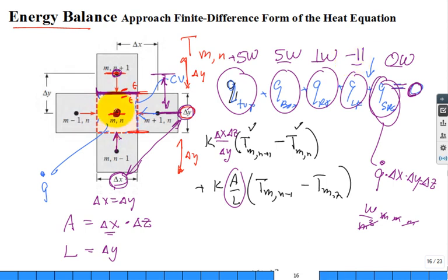So what you do is you get an equation, I call it energy balance for the node, let's say node 1. Then you get an equation for energy balance node 2, then energy balance node 3. You know what? If you have 10 unknown temperatures, you need 10 energy balance equations. Then, glad you took a numerical methods class, you'll have 10 equations and 10 unknowns.